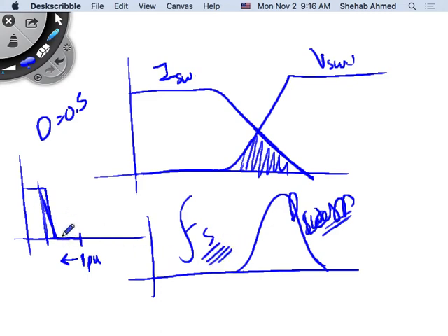Also, there's a limit on switching frequency related to your amount of power losses. You can play with power losses, because I can put in a cooling system, but then you're adding something big. Even though you can tolerate more power losses, you end up with a big piece of equipment, so you lose the benefit of increasing switching frequency to decrease the size of your LC. It's a big compromise: the smallest package possible versus the most efficient package possible.